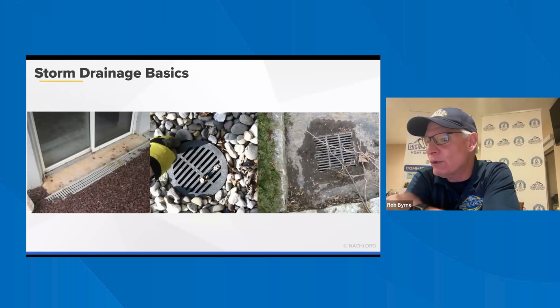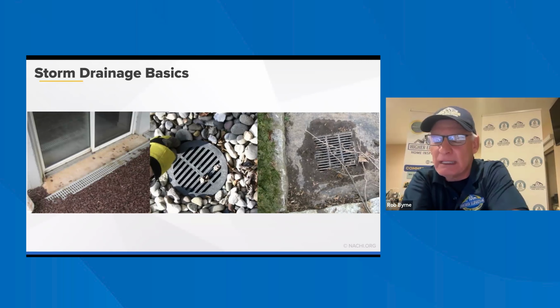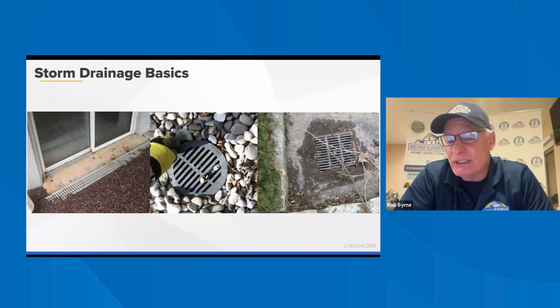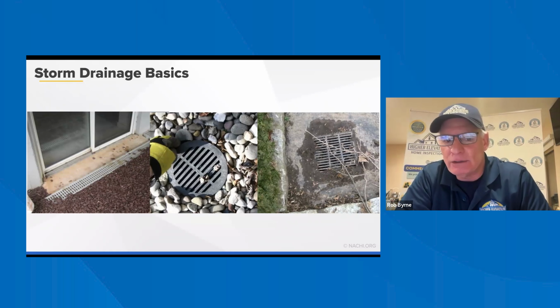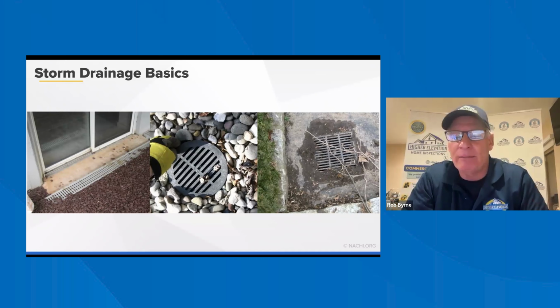Storm drain, rain, and groundwater should not be drained into sewer systems. They used to do this back in the day, in the boroughs where we do a lot of inspections in Brooklyn and Queens, and sometimes the older houses still have this, where the gutters and leaders are going down into the sewer system. So what the city realized, that you're sending all of this water that doesn't have to be treated to the sewage treatment plants. And they were getting overloaded when you get heavy rains, and you'd have problems with this. So now that's not allowed anymore.